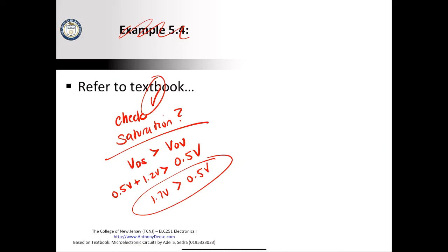Now, if that inequality was not satisfied, then we would have a problem. We would have to go back and redo the problem using the triode region of operation equation. Fortunately, that's not the case.